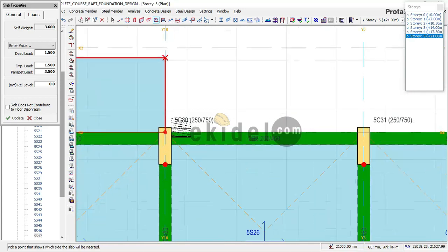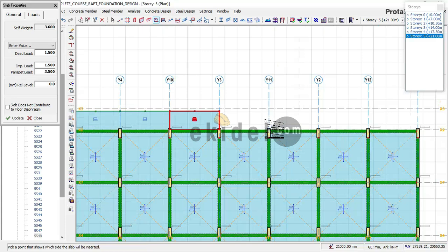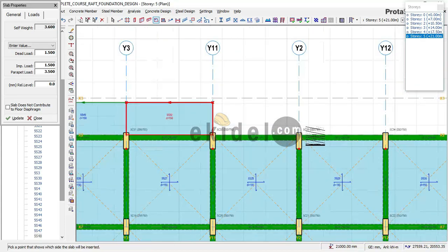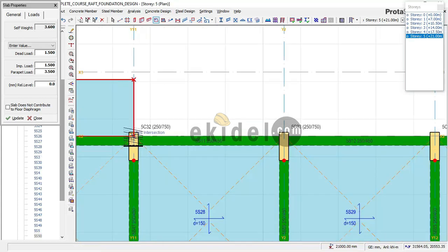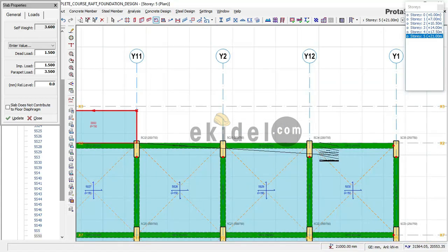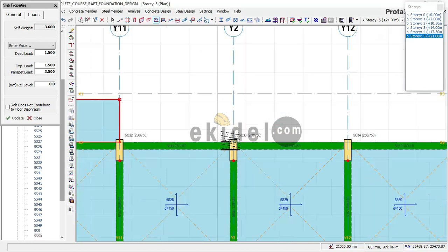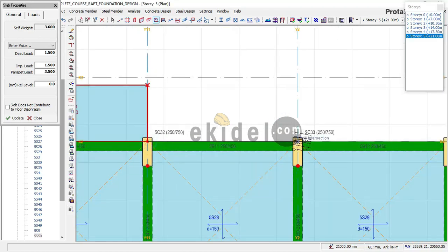So right now again, I'll begin to insert column to column, and you will see that we will have our cantilever slab all around the building. Let me be fast just now because it's the same step. Make sure you click from column to column. Don't click around this place, else this column will not be carrying that load. So make sure you transfer the load column to column. Let me do again, from here to here.